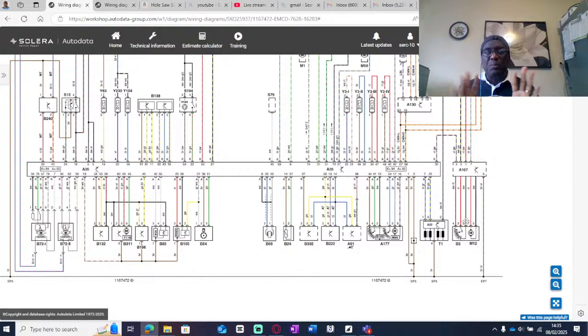They've stopped doing that, because if they make a mistake and say the wire is yellow when it's blue, and you're supposed to supply power, you scotch that ECU, and then you want to take them to task because they told you. I spoke to one of the salespeople, and he told me that they no longer show the colors, but sometimes it is handy to have the colors indicated, because it helps you a lot to fish out a wire quickly amongst a big loom like that.